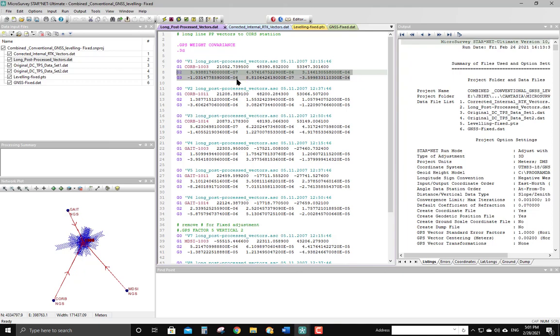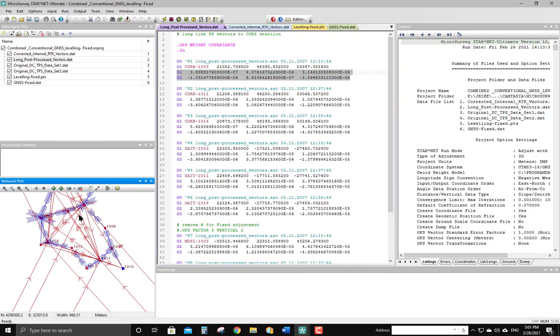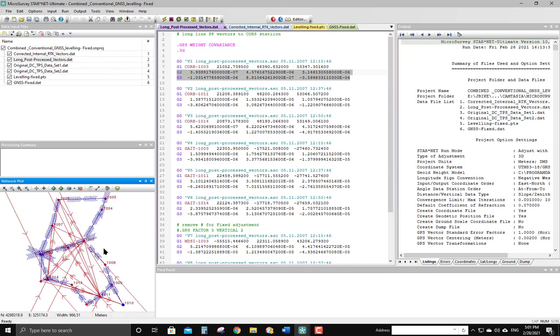So what we managed to do here so far is tie into some stations and generate a good location for our building site, and then use Traverse data to tighten up the internal accuracy right in here on the building site. So we've got both precision and we've got accuracy. And then a final step that was followed in this project is that leveling data was considered. Very often what will happen when there's precise leveling as part of a construction project is it's desired that the leveling data become the absolute authority for elevations.